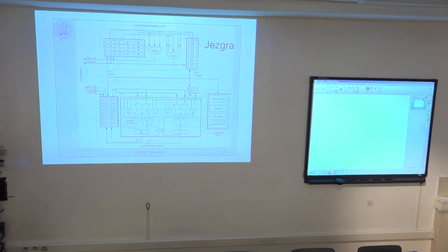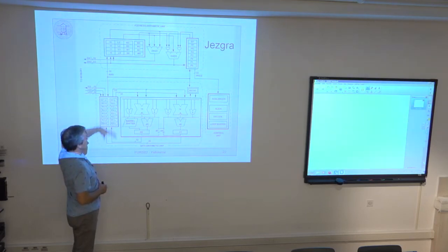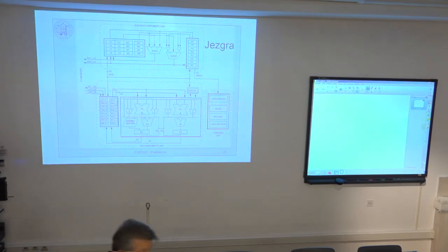And what this architecture takes as input value comes from this register file. It is like a universal data register file composed of 8 32-bit registers, R0, R1, R2, up to R7. Each of those registers can be invoked as one 32-bit value. If I say R0 is the argument of some instruction, or I can invoke as an argument only the upper word or lower word of this register, R0.high or R0.L.